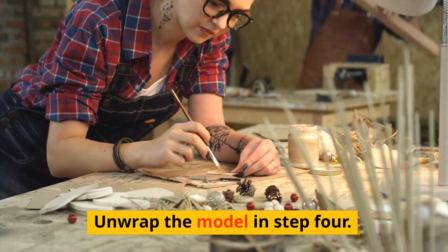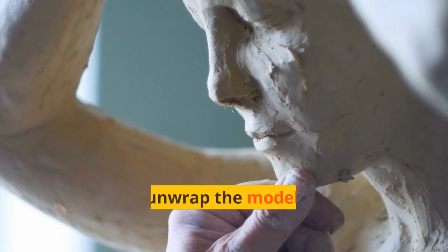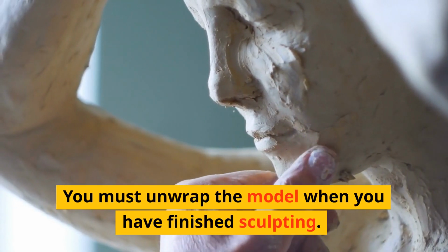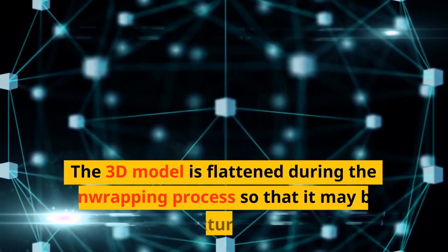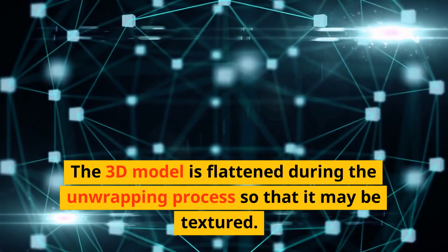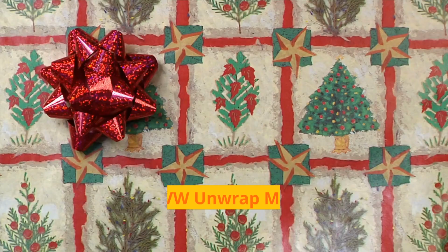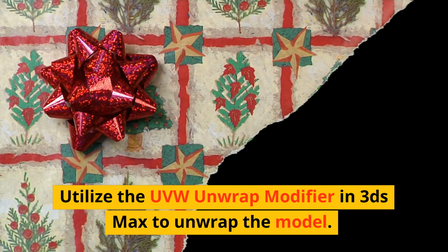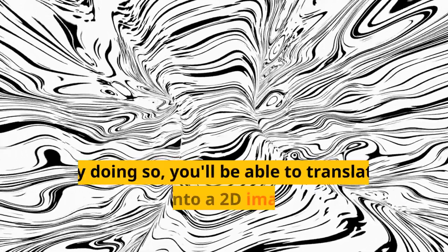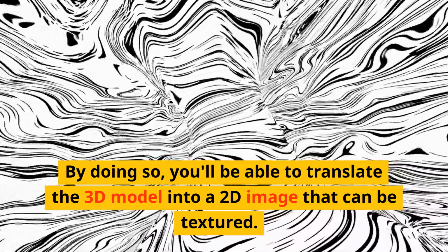Unwrap the model in Step 4. You must unwrap the model when you have finished sculpting. The 3D model is flattened during the unwrapping process so that it may be textured. Utilize the UVW Unwrap modifier in 3ds Max to unwrap the model. By doing so, you'll be able to translate the 3D model into a 2D image that can be textured.